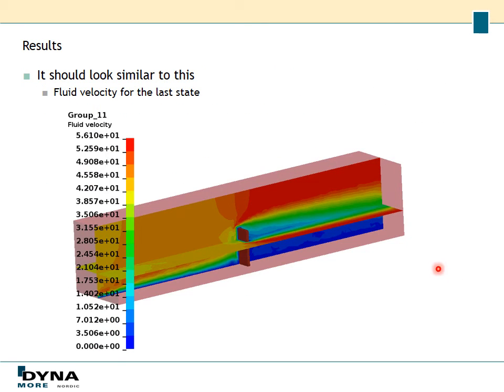And it should look something like this. So here we have 20 colors instead of 10, and two section planes but one legend, since we changed the properties of the group instead of each individual section plane.